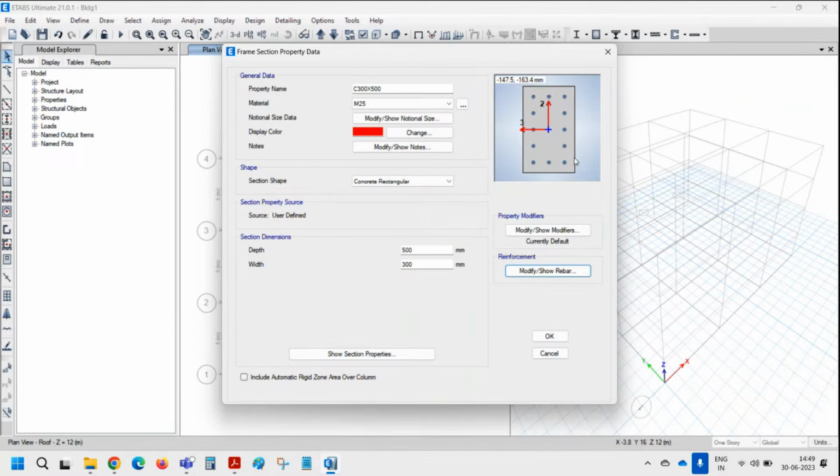You also have the option called SD section, where you can create an irregular polygon as a column shape and specify the rebars. So program will generate PMM interaction surface based on compatibility method and use it for the design. Right? And this will be more realistic than simply rebars distributed on 2 sides or equally on all 4 sides. Right.